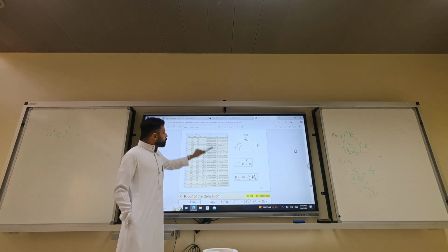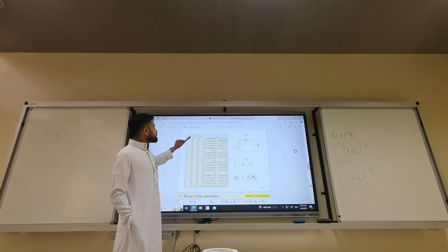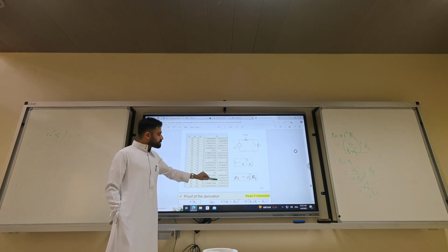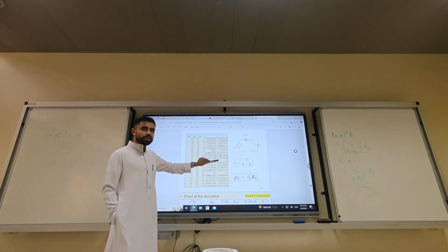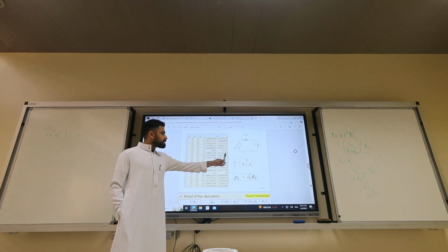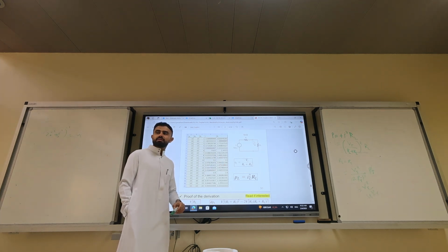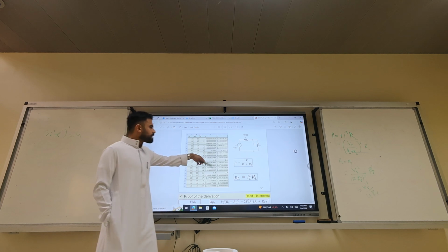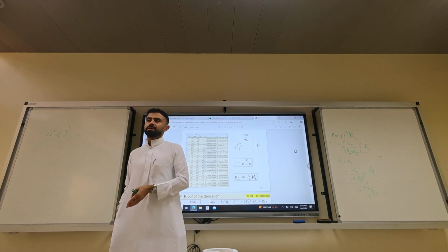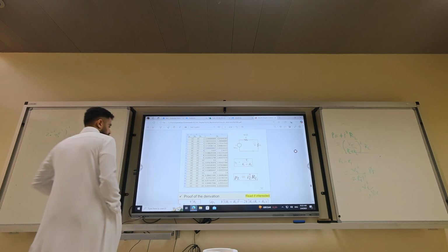If you go below RL, the power decreases until you reach RL equal to 0, where you get 0 power. If it increases, if you're becoming so needy in life, then you will consume less power. So to extract the maximum, you have to be right around Thevenin, okay? And this applies to many concepts in engineering. The biggest value is not always the best. Sometimes something in the middle is what gives you the most. Get it?